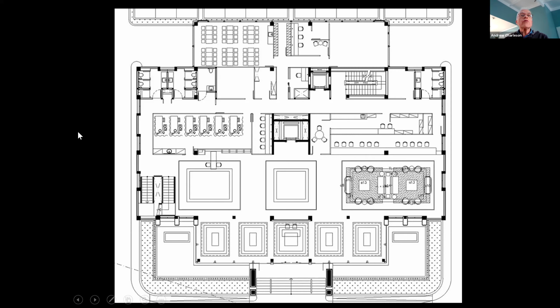What about the resistance in the X direction in this building? Well, we've got like one shear wall there. That wouldn't be enough because we need at least 2 structures in each direction. I mean, if we were going to use shear walls, we could have a shear wall there and, well, maybe a shear wall at the back of the building might be possible. And that could work for us.